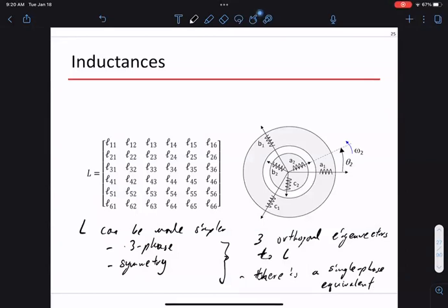So that's basically where linear algebra comes in. All you guys who learned linear algebra may think, why does it matter that eigenvectors span a subspace? It is actually used every time you use a motor. That's where it comes into use. For people who have taken power electronics, there is something called the DQ0 frame, the Park transformation, if you have seen this.